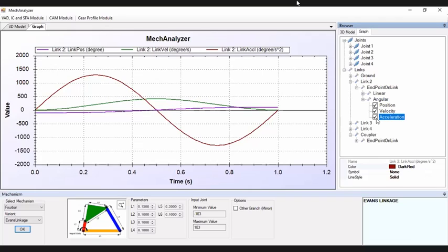Then acceleration is like this. So initially it will be 0, and at the end it is 0. So all these things we check when we are actually planning the path. So the path that your mechanism follows should be smooth. Okay, so you just have to go one more step from here after acceleration, like you also have to check jerk and snap. So instead of just differentiating two times, you're differentiating 3 or 4 times to check jerk and snap in your mechanism.